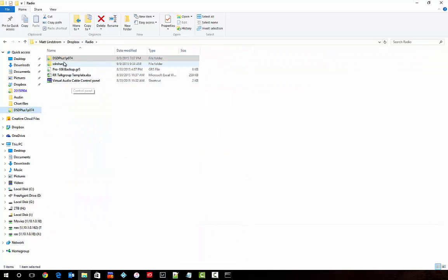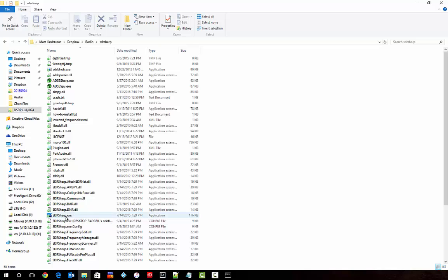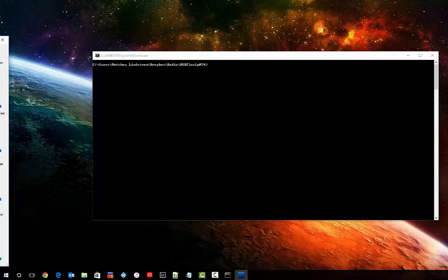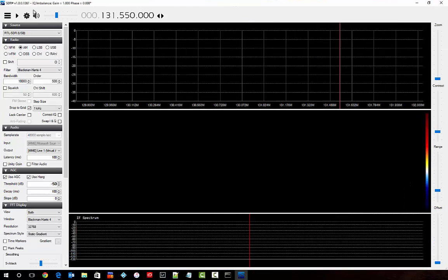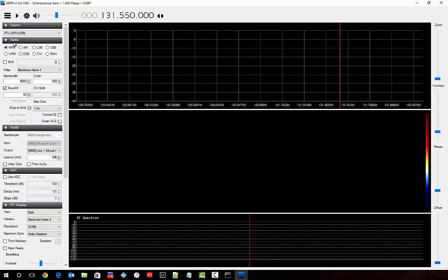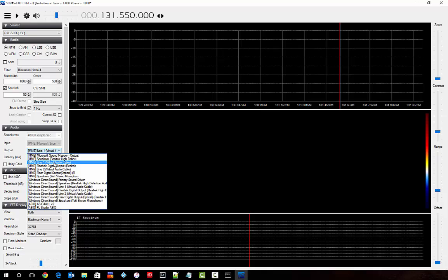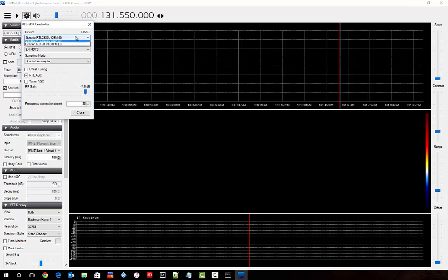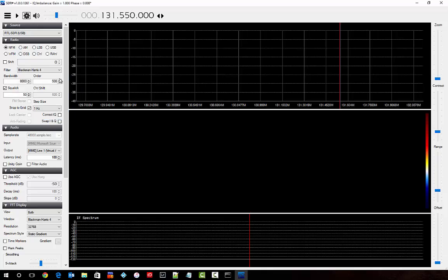And we'll go ahead and get SDR Sharp fired back up on this machine, and we'll make sure that we're using the right dongle and that sort of thing. Okay, so I have SDR Sharp open over here. Got RTL SDR selected. I want narrowband FM, snap to 1 Hz. I still have my line 1 virtual audio cable selected as the output. And I'm going to choose device 0, which should be a plus 68, but we shall give that a try and see where we are.